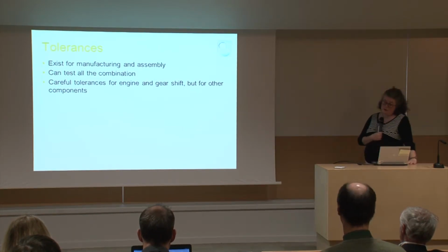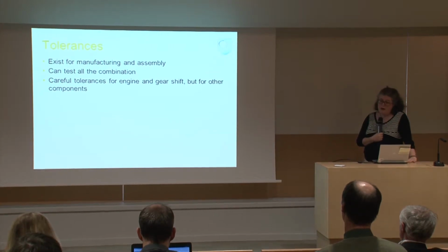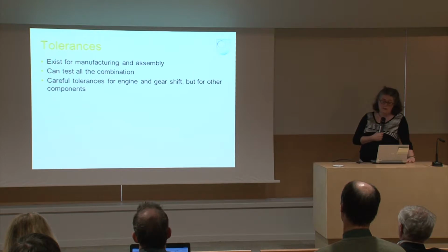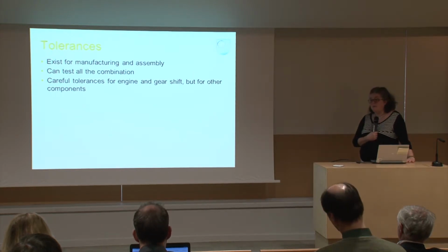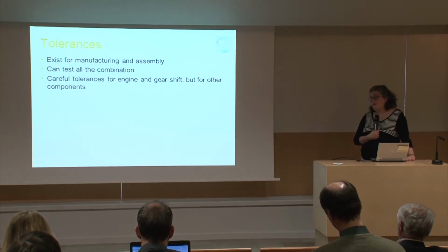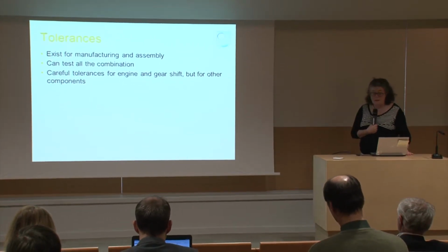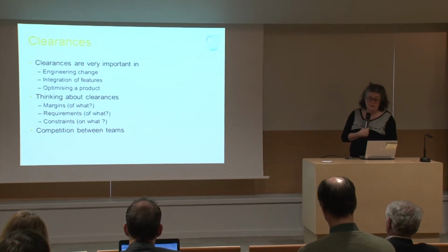Another source of margins are tolerances, which on one level are of course something very different, because they're added for manufacturing purposes. And normally tolerances are very small and margins are potentially quite big. But of course, if life gets really critical, then the design margins and the tolerances meet, and you might actually jeopardize your manufacturing quality. So this is something that could be quite an issue.